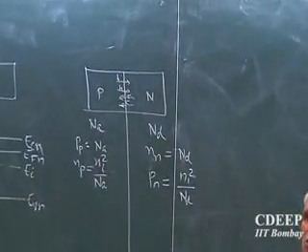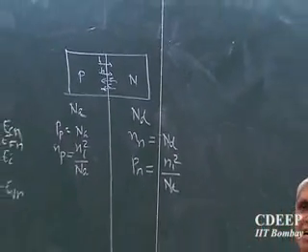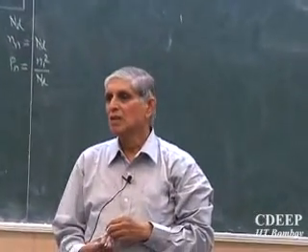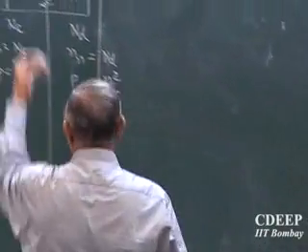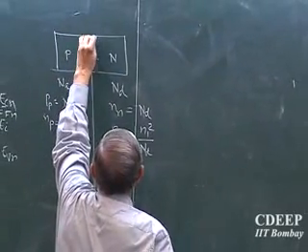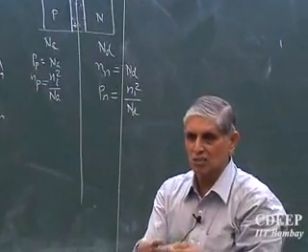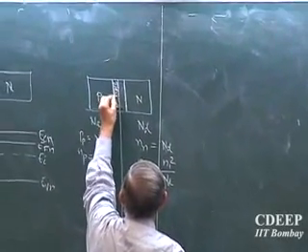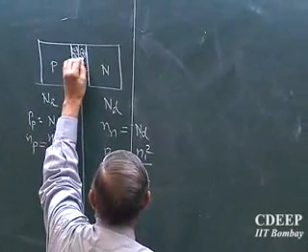This process is called diffusion. They will diffuse. But whenever electrons leave the N-type or holes leave the P-type, what do they leave there? Ions. They will leave ions. So if I expand this area, the electrons which are very close to the junction will go first. As soon as holes left there, acceptors appeared. Wherever electrons left, donors appeared.